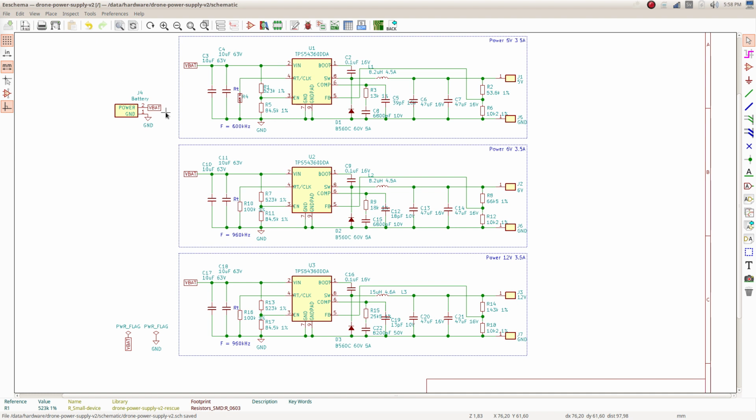So, for example, the components that I'm using here are not very useful for somebody else who is designing a schematic, because that person would have their own suppliers, that person would have different manufacturer numbers, so they have to go through that process themselves, and they have to make their own library where they put all the fields in, where they have well-defined components with pre-assigned footprints, which they can then use in different designs. And I think that this is something that every designer should get really comfortable with. As a designer of a schematic, when you draw the schematic, you really have to get comfortable with designing your own components and putting them together on your final schematic.